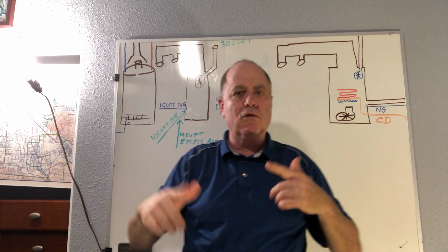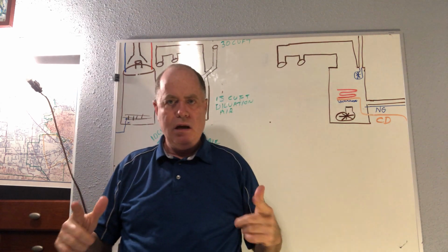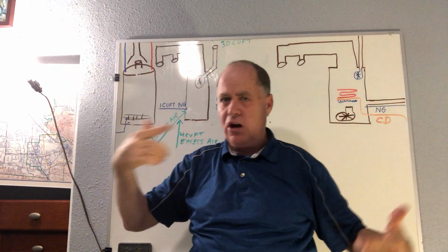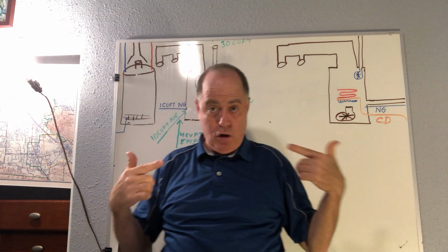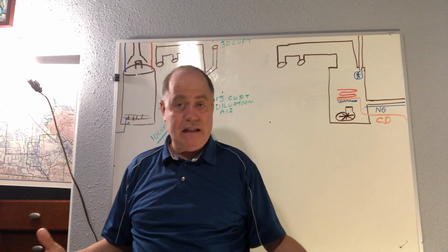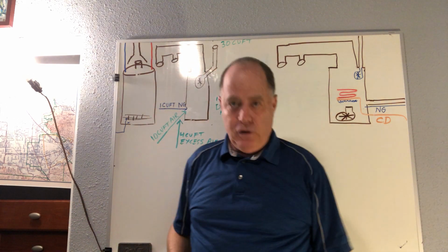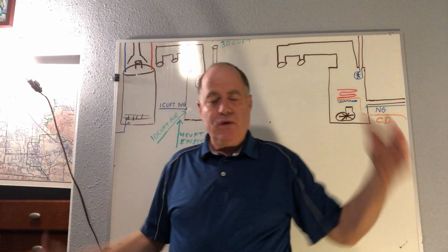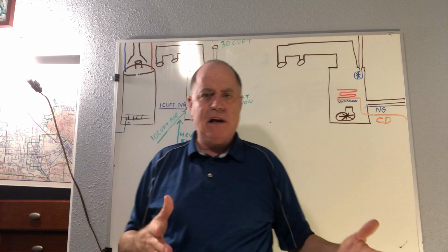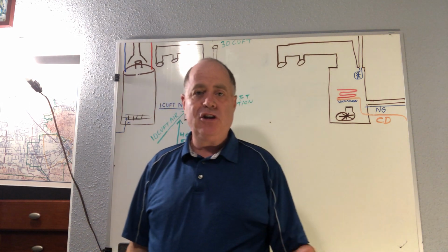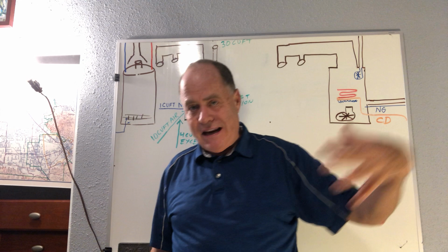That's so your garage can stay ventilated, so the air comes in, warms up, and then goes out those vents. Because people start up cars, they work on projects, they spill gasoline, they have paint. Also, if you have a furnace or a hot water heater, you can't have the garage totally sealed up and then run it, because it's drawing its air from the garage, so it needs a source for that air to come in.